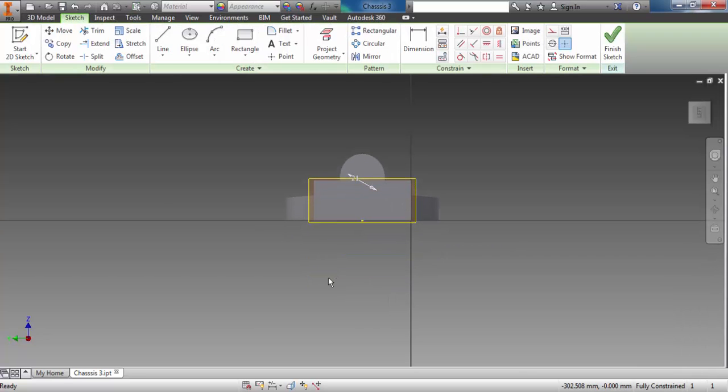We create a sketch, and the sketch that we're going to create is going to be an ellipse. So from the circle menu we can choose ellipse. So around about the center, we're going to click once, move to the side, and left click again. Then we're going to drag the ellipse up until it is just slightly above the top surface of the chassis.